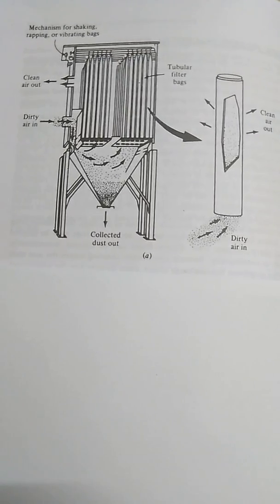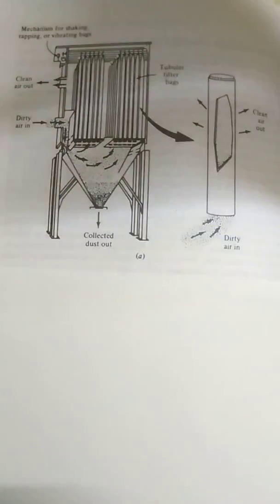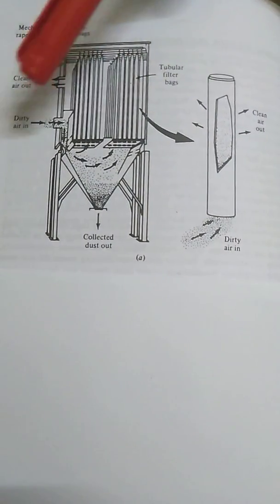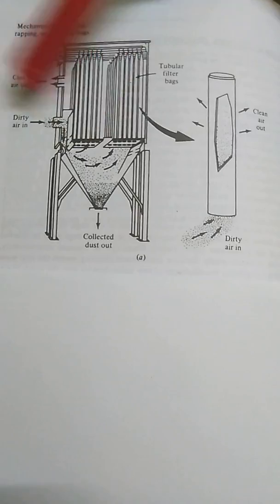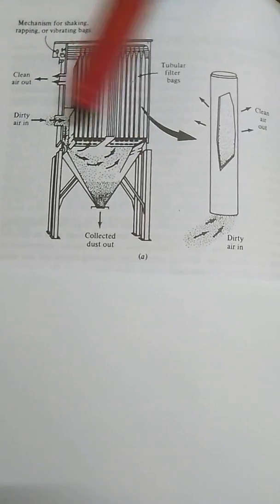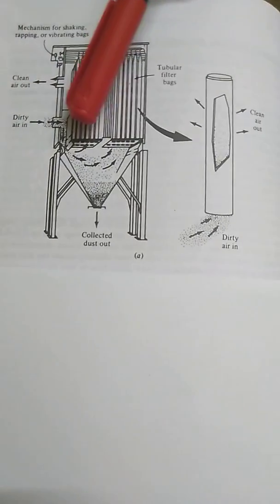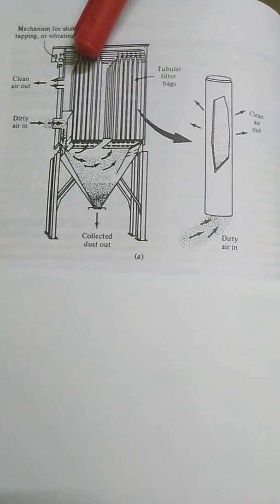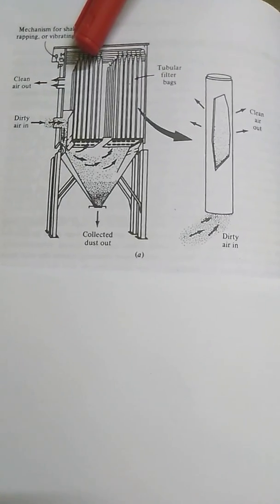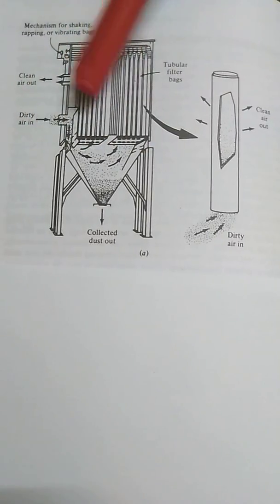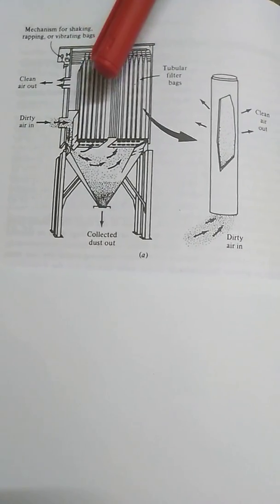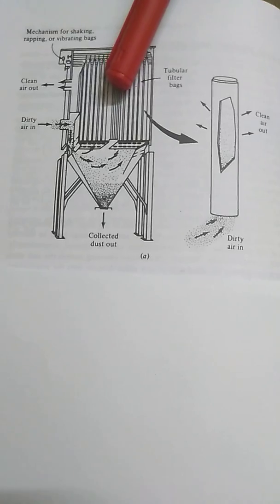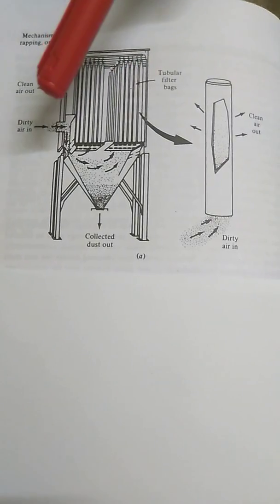And efficiency during the pre-coat formation, that means when we enter the fresh air after cleaning, at that point the efficiency of suspended particulate matter removal will be very much higher, because the pores are clean, or not having any suspended particles in them.